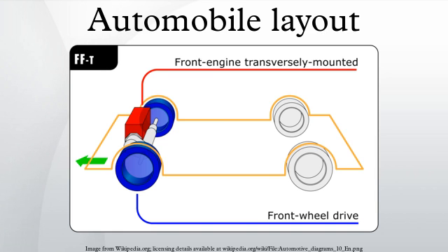Decreased interior space. Though individual designs vary greatly, rear-wheel drive vehicles may have less front leg room as the transmission tunnel takes up a space between the driver and front passenger, less leg room for center rear passengers, and sometimes less boot space. Rear-engine designs do not inherently take away interior space. A rear-wheel drive vehicle with four-wheel drive, compared to a front-wheel drive vehicle with four-wheel drive, will have a less efficient interior packaging since the transmission is often under the front passenger compartment between the two seats, whereas the latter can package all the components under the hood.